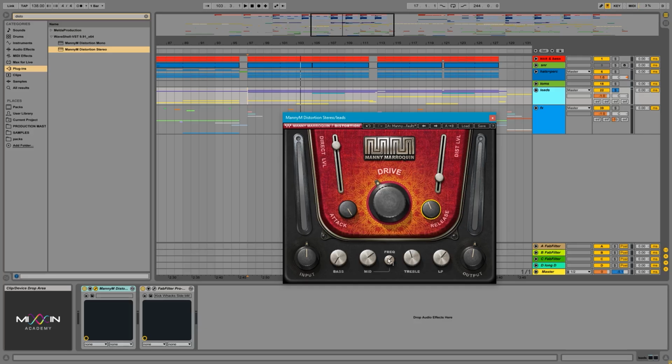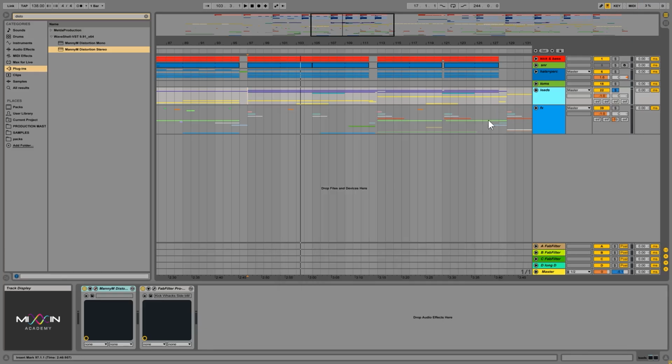And we also, as I explained, have this EQ, which is the bass, mid, and treble. Both of these, I presume, are shelves. So shelving filters for the bass and the treble, and we have the mid one, which actually has adjustable frequency. It's probably a bell filter. And we also have the low pass on top of all of that. Of course, we have the input and the output gain regulation right there with those two parameters.